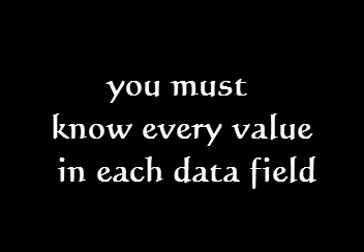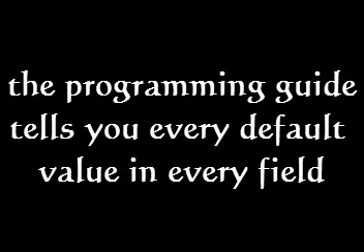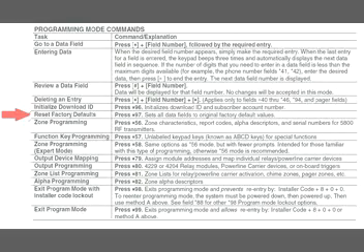I'd like to mention factory defaults at this time. I've spent months reading online forums about the problems you can have with alarm panels. And the vast majority of the problems seem to stem from programming. Specifically, a data field was set to a value the programmer didn't know about. The easiest solution to this problem? Reset the panel back to factory defaults. This is how you do that.